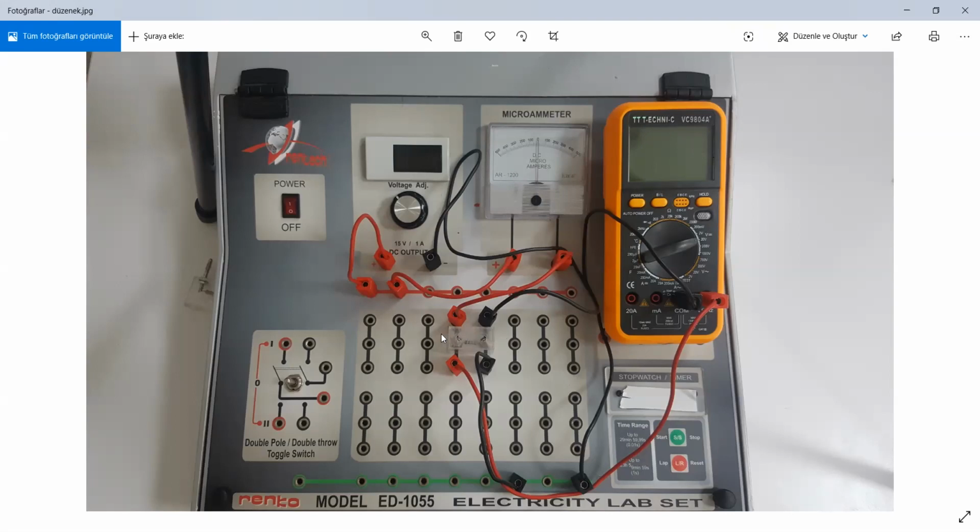When we set up the circuit, we connected the plus terminal of the power supply to the red slot. Since on that board, slots lying on colored lines are interconnected, we connected the ammeter in series with one end of the resistor. Then, using the green slots, we connected the minus terminal of the power supply to the other end of the resistor.